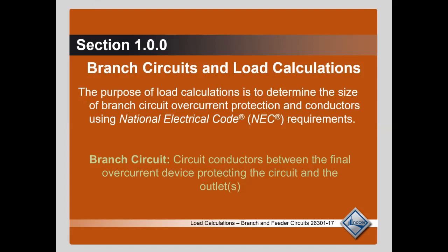So if I know that in this building, office, home, whatever I'm at, if I know for a fact that this circuit's going to run, let's say, an air compressor, and I know air compressors pull approximately 12 to 15 amps of power, depending on the size of the compressor, then I'm probably going to make sure that that's either a 20 or 30 amp breaker.